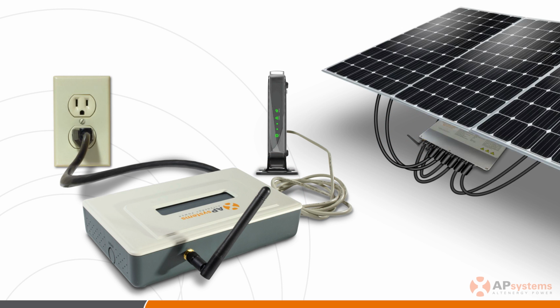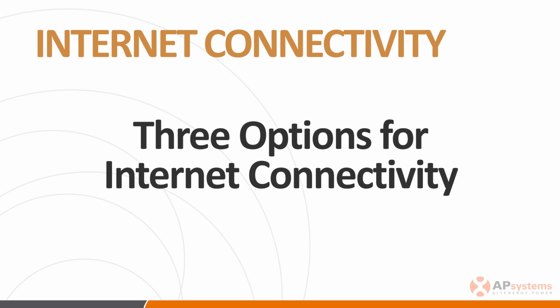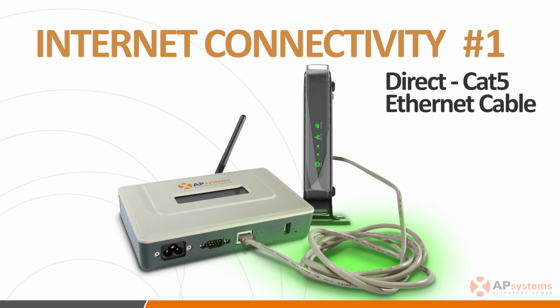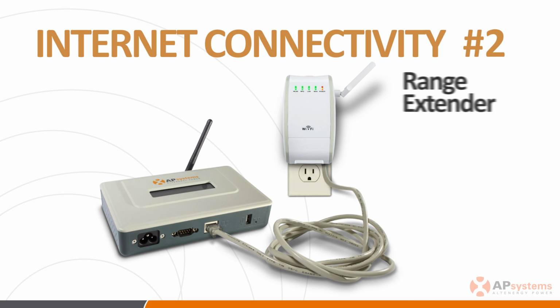With a stable Zigbee communication established between the inverters and the ECU, connect the ECU to the internet using one of the following three options. Option 1, which is the most straightforward approach, although not always convenient because of the ECU placement, is to use a direct Cat5 Ethernet cable connection between the ECU and broadband network router. Option 2 is to use a Wi-Fi range extender to wirelessly connect the ECU to a wireless broadband network router.